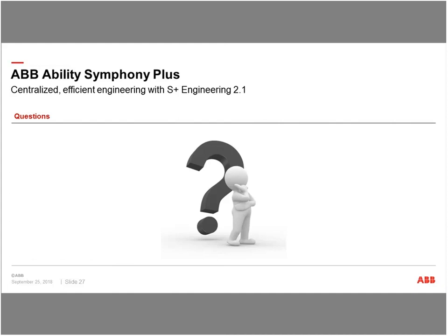And then a question about 800xA as opposed to S+ Operations for tag database integration. For 800xA, this new operation engineering only works for operation 3.1. So for 800xA, it basically works as before. You still need to work in control engineering or the Composer database to define all your tags and then export to a file, either MDB or Excel. Excel, yes, and then you need to import into the 800xA aspect server.